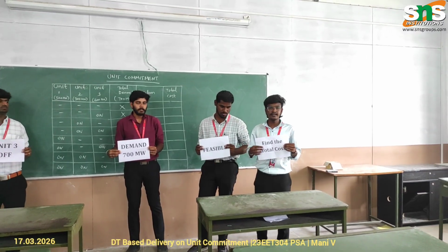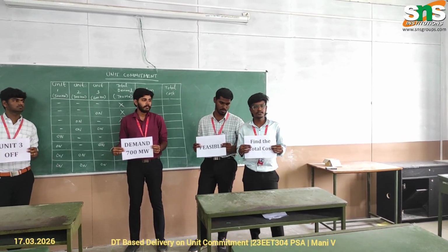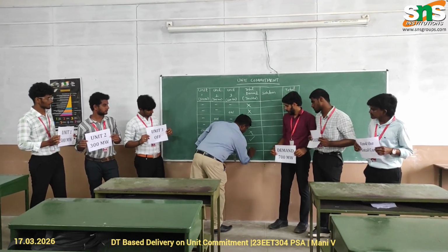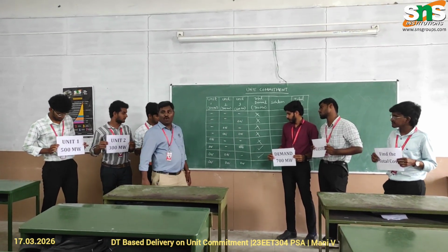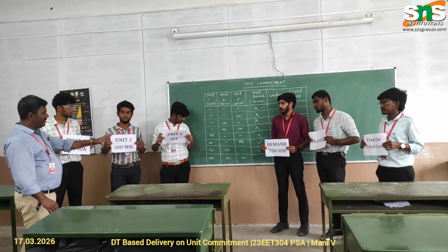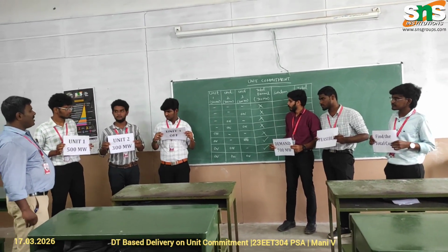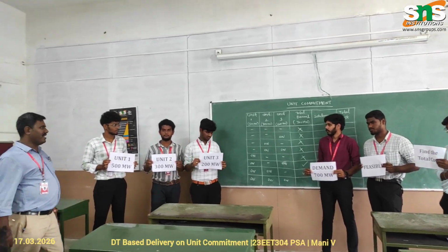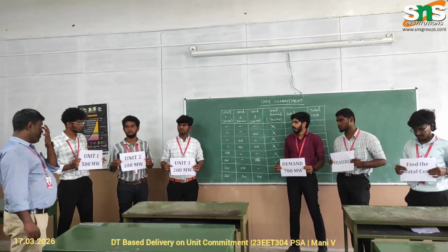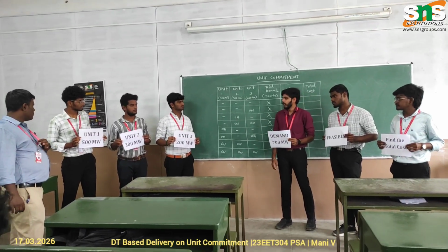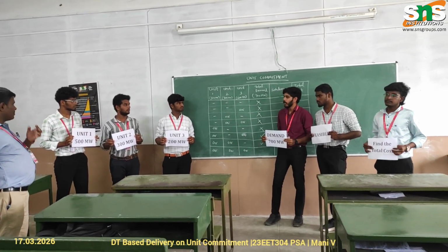It was feasible. I need to calculate the total cost. Fine, so we are getting one more feasible solution, because the generation is 800 megawatt, but the load is only 700 megawatt. And another one: unit 1, unit 2 and unit 3. All three units are operated simultaneously and start producing the maximum capacity. So these three units are turned on and producing 1000 megawatt.